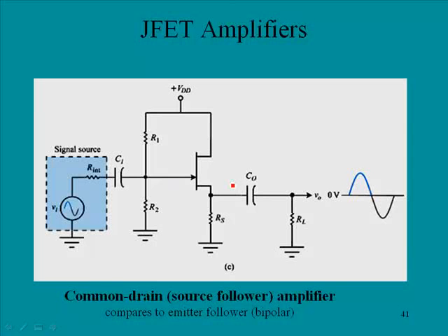Now again, in this configuration, much like the emitter follower, there was no gain here. The thing that we got from this circuit was that it dropped the output impedance down very low so that we could couple most of our signal to, and here we have a load right here. This provides for excellent coupling so that most of the signal is not lost on the amp but is delivered directly to the load. And this type of amp is very popular with high power amplifiers.